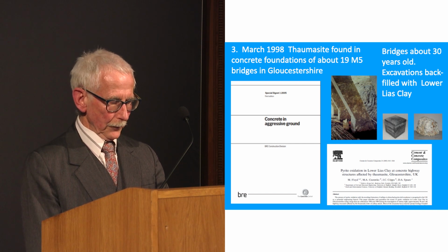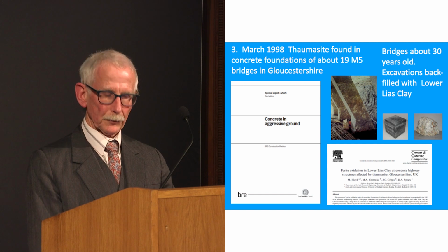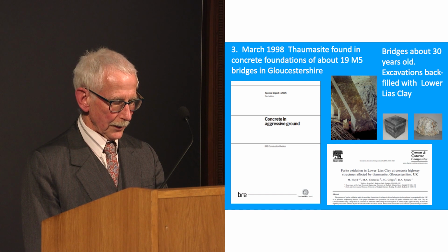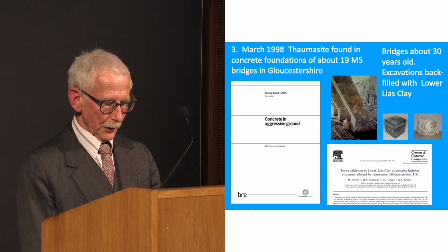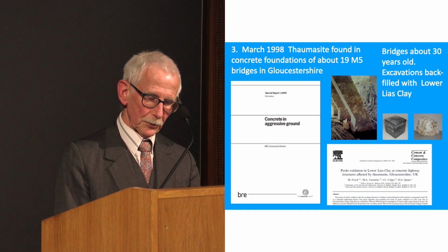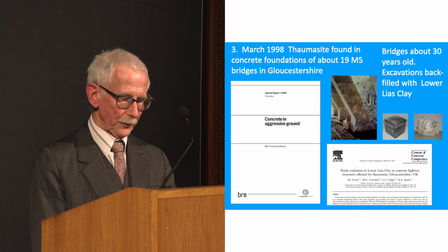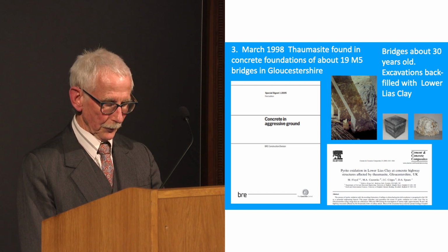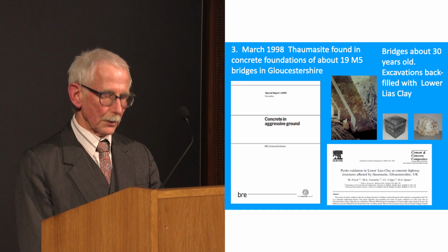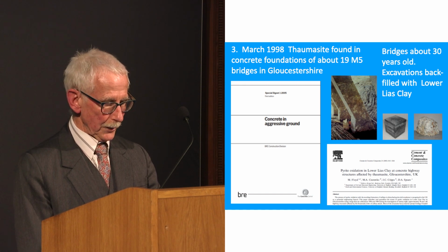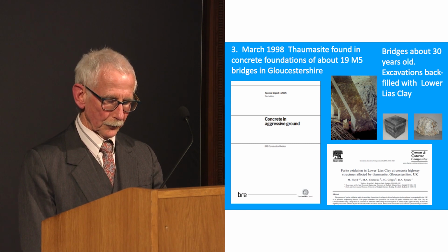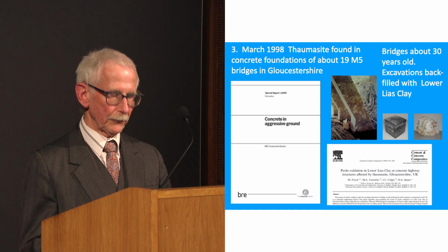The lack of attention to pyrite was remedied by the publication of Building Research Establishment Special Digest 1, which sets out procedures for classifying aggressive ground and the design of concrete that will resist such conditions. Various investigations into thaumasite formation and the effects of clay weathering on concrete were carried out at Sheffield and other places. One of the results was that sulfate-resisting cement is not immune to thaumasite formation, and that the presence of chloride, either from poor water or from road salt, changes the vulnerability of the concrete to damage.